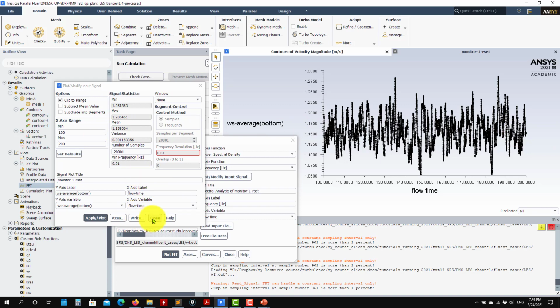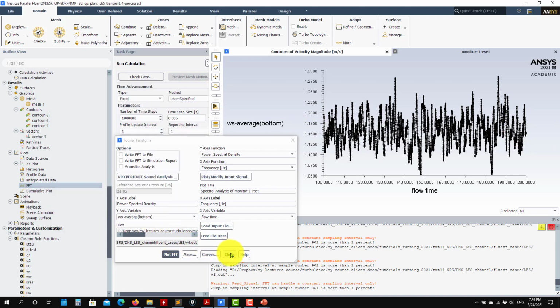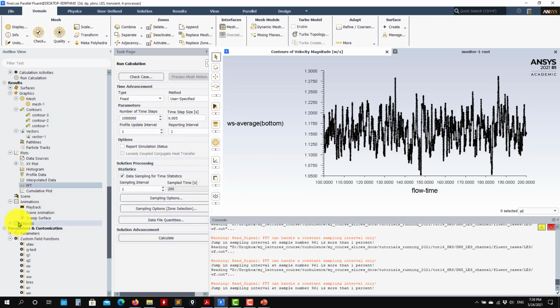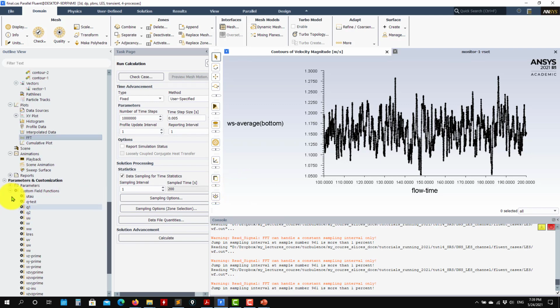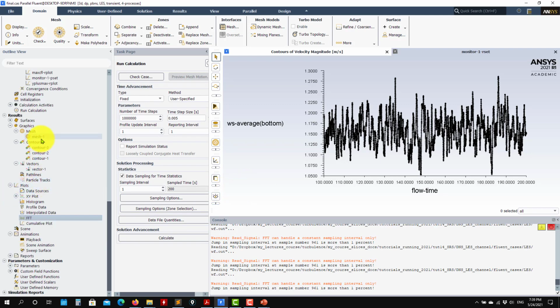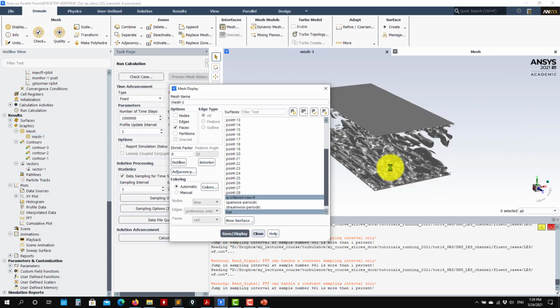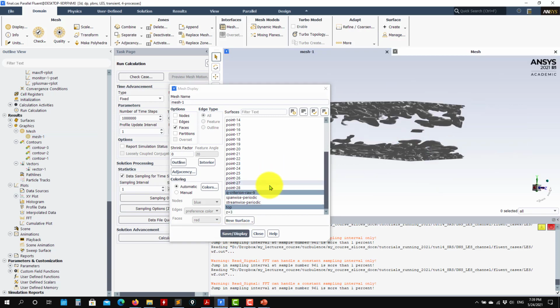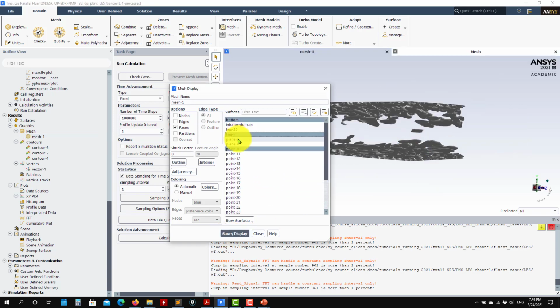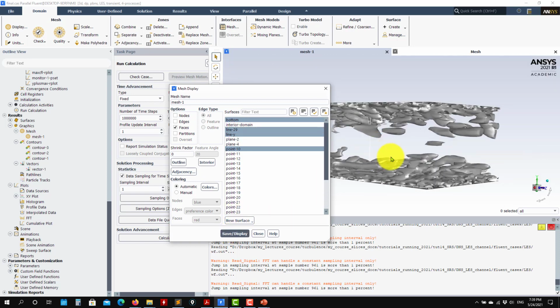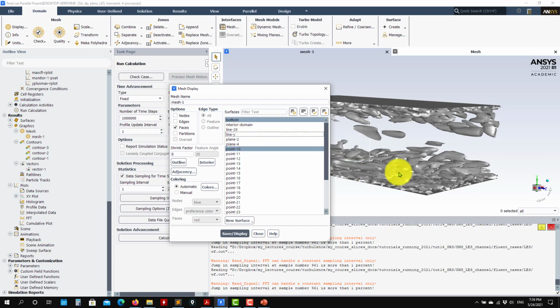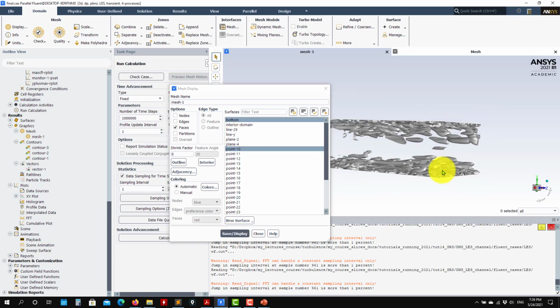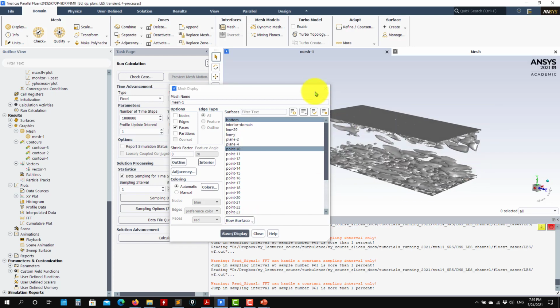So you have everything here. And for instance, remember that we can do some plotting of the normalized velocity profile. In this case, I have a line there. I'm plotting these profiles. And see that I have here also the Q criterion to visualize the streaklines.